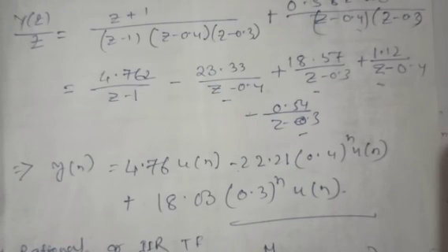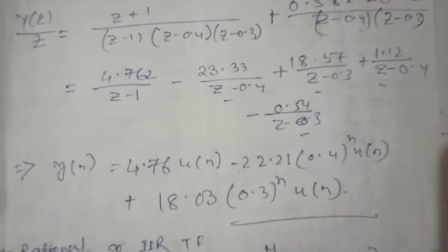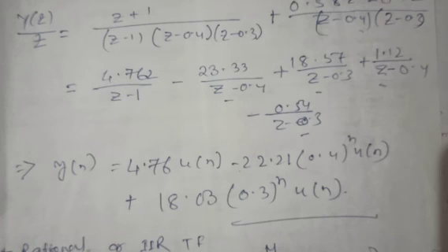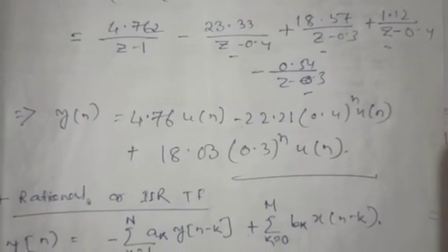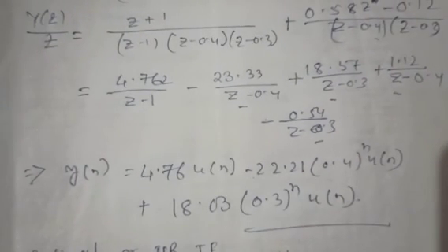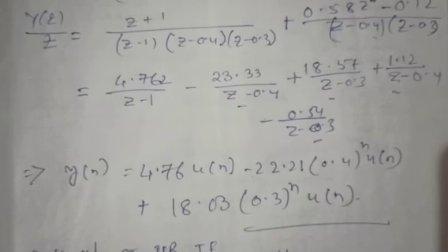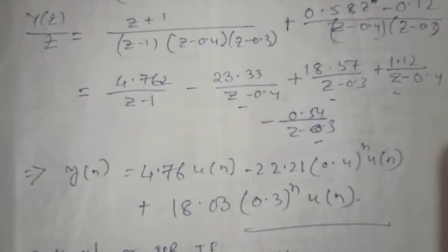Okay, so for that you need to take the Z transform of the whole equation. Okay, then if it is forced response, then put the transform of the input instead of X of z and do the simplification, and finally do the inverse Z transform to get y of n. Okay, so this is how we do the analysis of the discrete time LTI systems in time domain.